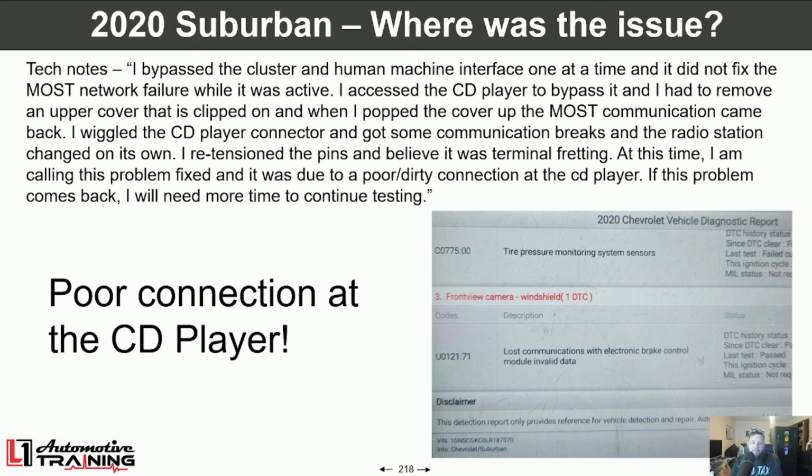This was a pretty basic diag of a MOST bus, but if you weren't aware of how the node system operates, it could be pretty difficult to pick a starting point in knowing what does and does not communicate, right? You've got a sealed system that you can talk to one single module of the radio.